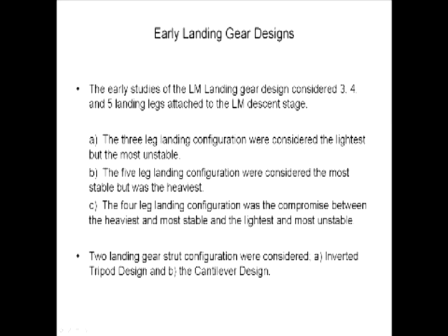And again, there were 2 basic designs. In the inverted tripod design, all of the struts attached at the foot pad, whereas in the cantilever case, the 2 struts were attached to the primary strut. That gives you a little bit more room in case you hit a boulder or something; you wouldn't be poking a hole or breaking one of the struts if they were up higher off the ground. And you can see in the configuration later on. Next chart.